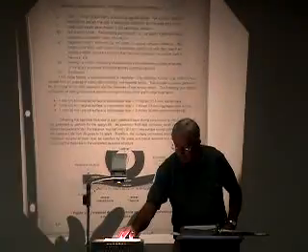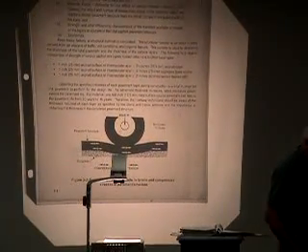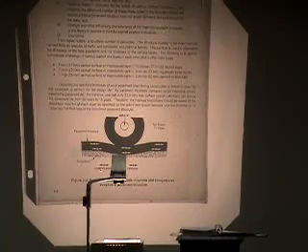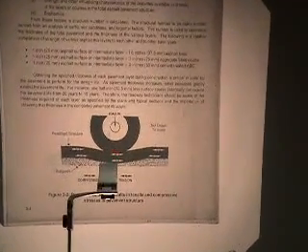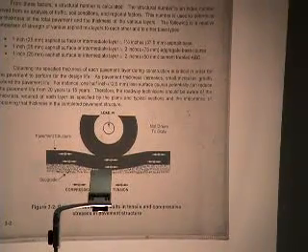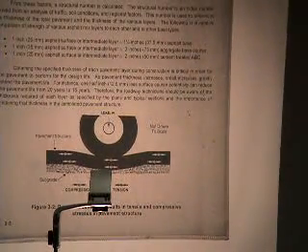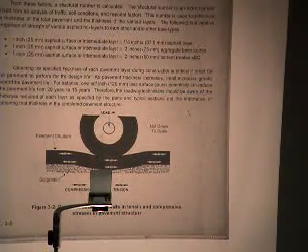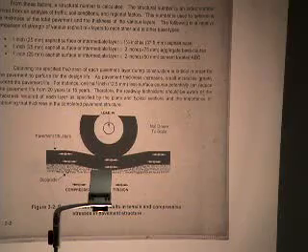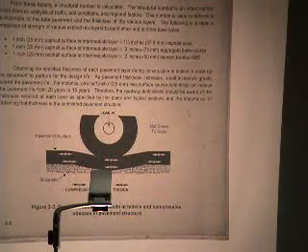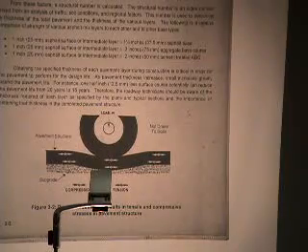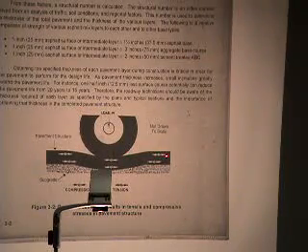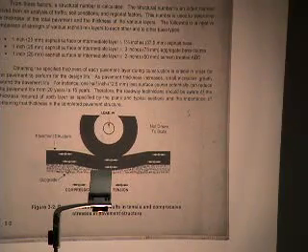Down at the bottom of that page, you'll see that tire load being applied to the pavement again. And when the tire load is applied, there's some deflection that occurs. Hopefully this is exaggerated for illustrative purposes. But when it bends directly under the tire, the upper portion of the layer will be in compression, the lower portion in tension. And because the curvature is the opposite out on either side, the reverse is true.